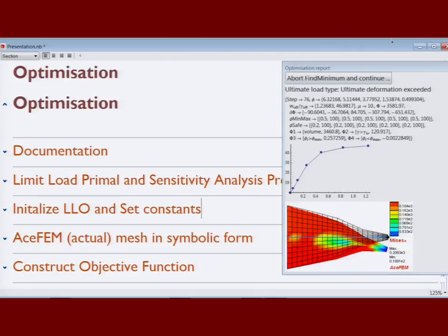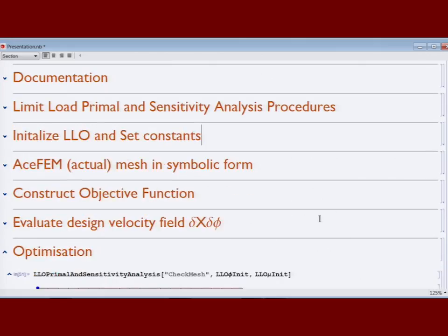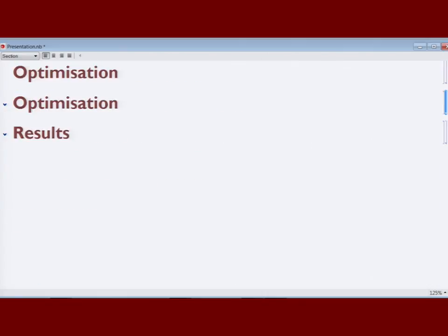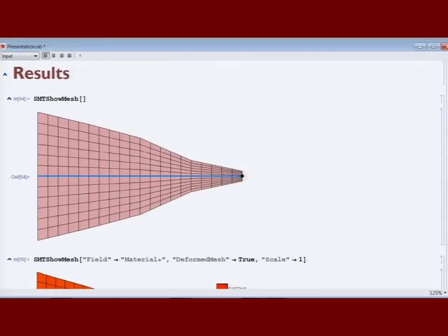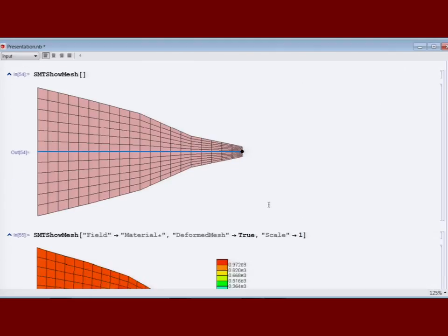So we can look at the results. This is the shape. It might be more straight, but here is this technological constraint. I put in that there has to be some minimum height of the beam at the end. Otherwise, the analytical solution is a pure triangle, actually, if you would do this analytically.